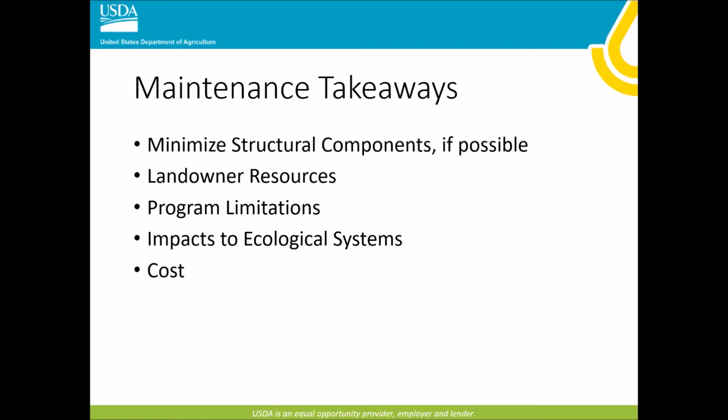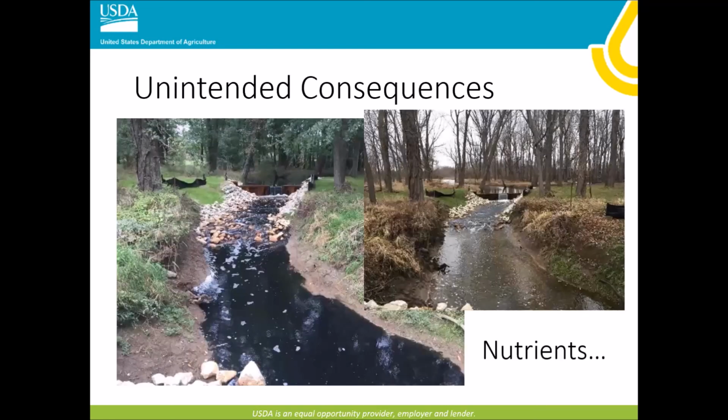And then to finish it up, one more slide there, Bree, is the unintended consequences. I'm just going to highlight one unintended consequence of a wetland restoration project. That's not oil right there. It was thought that there was oil on this wetland, but at this wetland site, we ended up putting a sheet pile structure in the middle of the ditch. Upstream of here was a very old degraded wetland that had scoured from an erosion cut and wasn't effectively holding water anymore. So the plan was we'd put that sheet pile structure in there.